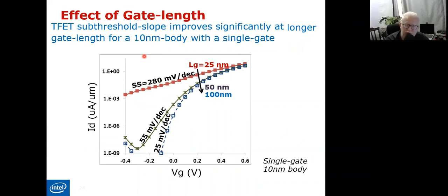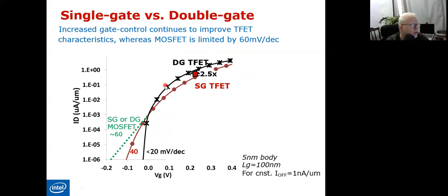Accordingly, we can have characteristic curves to demonstrate the properties of this tunneling field effect transistor. Also, maybe as you did in your projects on some devices, what we are going to do now is just to optimize the device. For example, here, this optimization is in terms of the gate length. So they are changing the gate length and they see the effect on the transistor at different gate lengths. Here we can express the effect. And also maybe here we have different characteristics by different materials, I think, and also by different, let me say, what is the variable here?